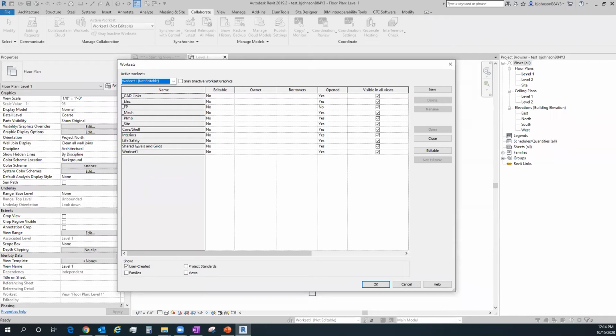So setting up work sets correctly is probably one of my highest level tools to define problems when Revit crashes, because I can drill down to exactly which component, whether it's an external file or a core and shell object, if it's an interior object. If I had a life safety specialty item for egress tracking or symbols that's causing the problem, chances are I can find it there.